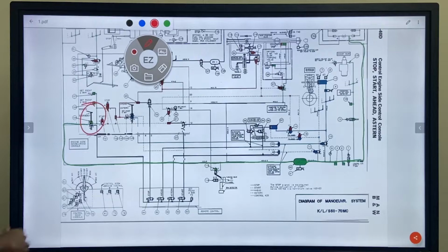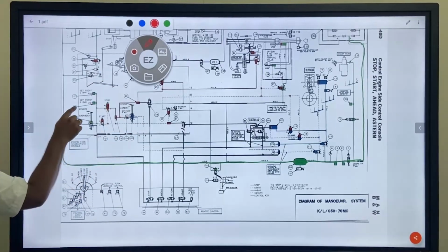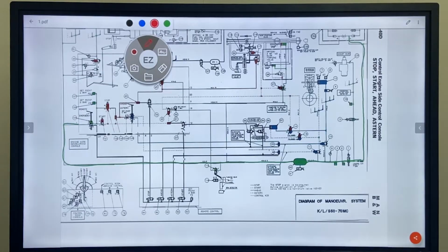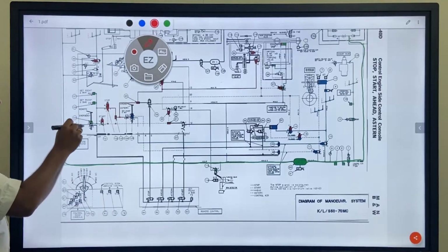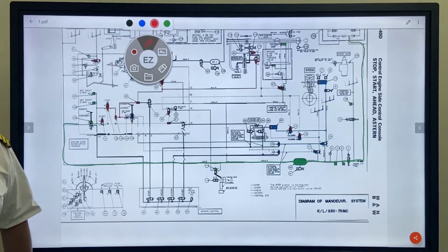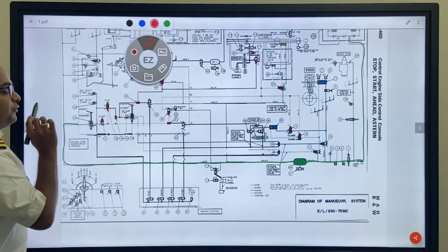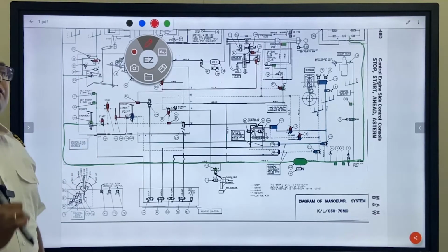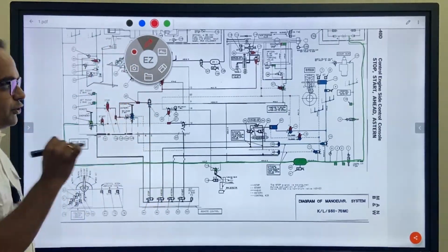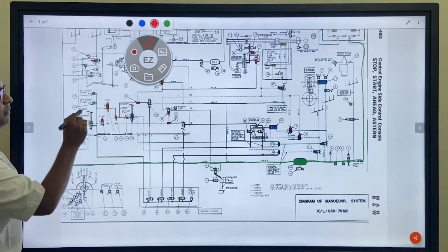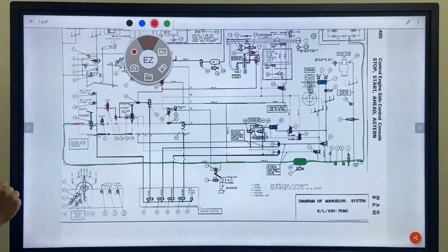What is this point? This is the selector switch. If you can read over here, it's remote or emergency. Remote means it can be started either from the ECR or the bridge. If I select emergency, then it can be started only from the local, meaning the engine emergency console of the engine. We are dealing with starting our engine from the remote condition, so we'll first choose the remote one. We'll assume that this valve is set at the remote condition.